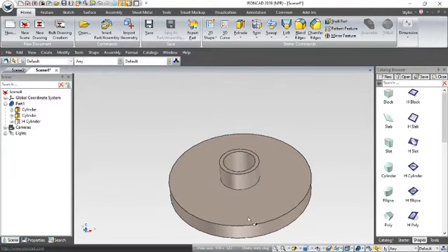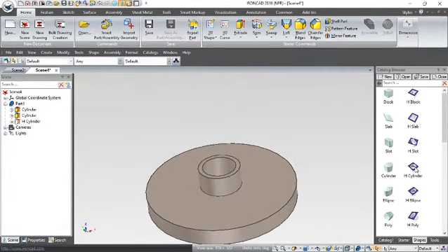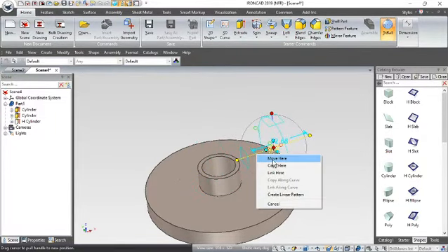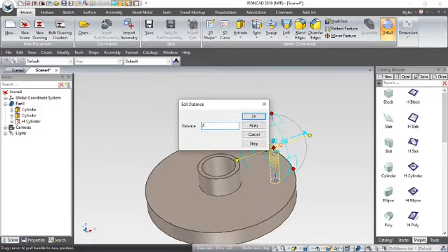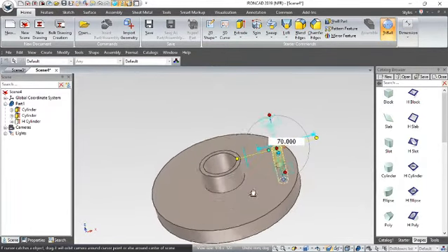And say this wants to be a flange, so maybe you want to put some holes on a PCD around this cylinder. That's very easy to do. We can go to the hollow cylinder, and I'll just pick it in here and put it there like that, and maybe I'll make that 12, hit return, press F10 to bring up the tri-ball for that hole. Now on this outer axis, I'm going to hover over that handle there, press the right mouse button and simply drag it like so. Let go and select move here, and maybe I'll make that 70 as a distance, which is the radius for that hole on this flange. So it's positioned there now on the flange.